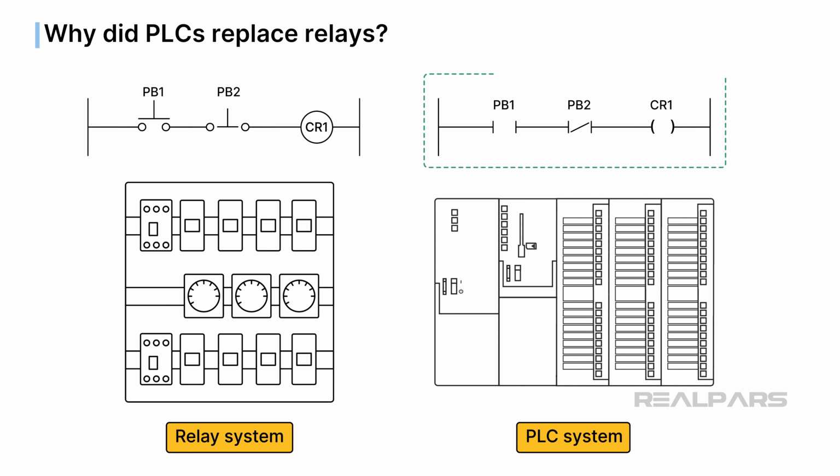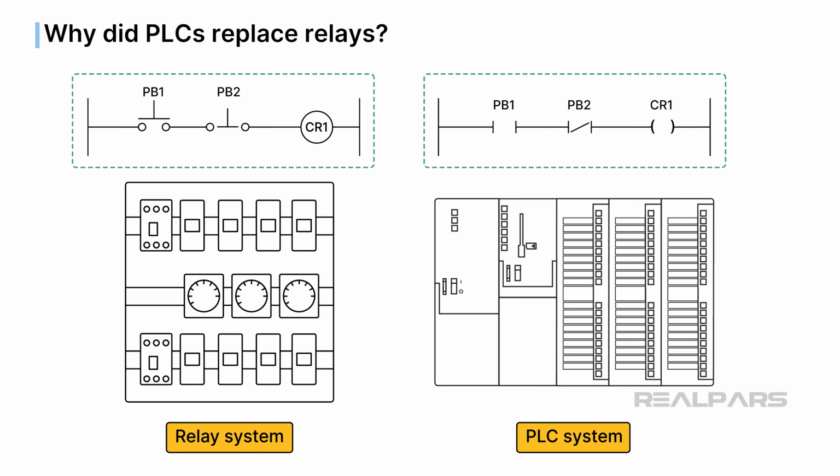Historically, ladder diagrams mimicked the wiring of relay systems, but if you understand Boolean logic, it does not matter if you are physically wiring relays or programming a PLC. You can understand what has to be done to make outputs come on and for a machine to change states.